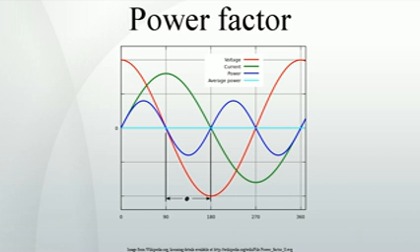Measuring the power factor. The power factor in a single-phase circuit, or balanced three-phase circuit, can be measured with the wattmeter-ammeter-voltmeter method, where the power in watts is divided by the product of measured voltage and current. The power factor of a balanced polyphase circuit is the same as that of any phase. The power factor of an unbalanced polyphase circuit is not uniquely defined.